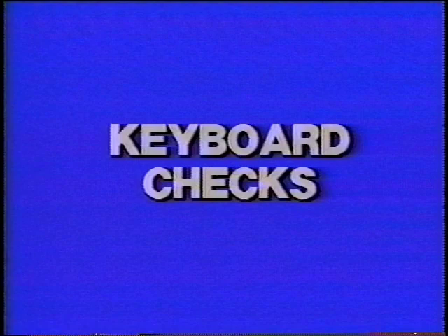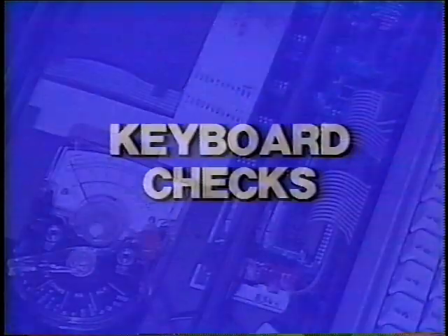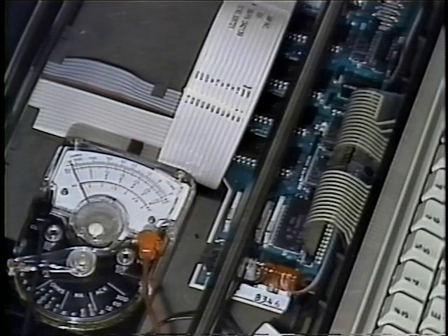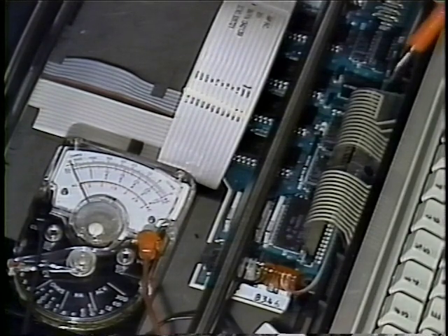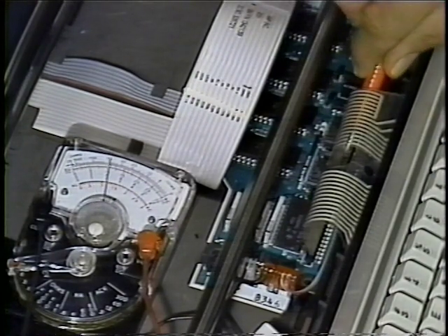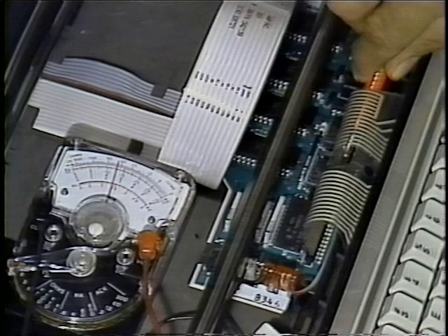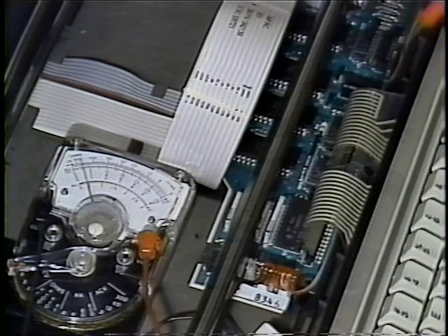In this section, we will discuss some diagnostic procedures for the keyboard and the indicator panel. To check a sense line, set your meter on the 12-volt DC scale and very gently probe the pin in the J2F connector for that sense line. The sense line should read from 4 to 6 volts DC.